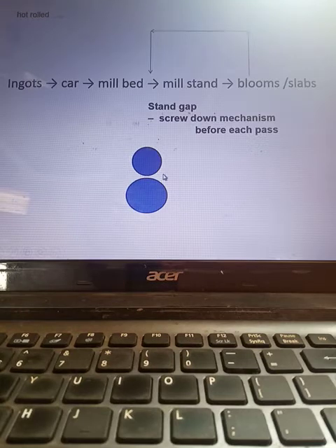The application is different, but here we are pushing an ingot of larger size. When it comes out, because of the pressure, the pressing, the shape and size will be different depending on our requirement. In the first go itself, we cannot have this space too small because the whole big piece has to pass through. That's why this gap between the rollers is kept larger, and subsequently that gap is reduced and we go on squeezing again and again.